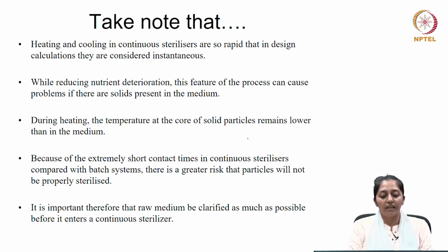Now, during heating, the temperature at the core of the solid particles will remain lower than in the medium. So, because of the extremely short contact times in continuous sterilizers compared with batch systems, there is a greater risk that these particles, if present, will not be properly sterilized.